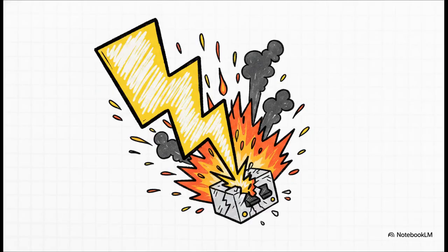You absolutely must use the subtransient reactance, X''D. Why? Because protective relays and circuit breakers are designed to operate incredibly fast. We are asking them to interrupt the fault in the very first few cycles. You have to size the breaker for the absolute worst-case scenario, which is the highest current it will ever physically see. If you use the steady-state synchronous value instead, you'd calculate a much lower fault current and disastrously undersize every breaker on your system. We're talking catastrophic explosions when a fault actually clears.